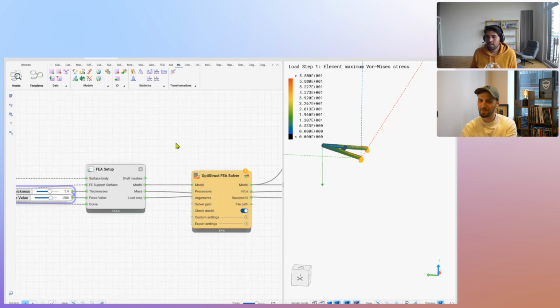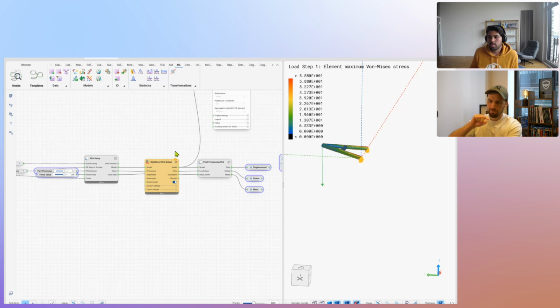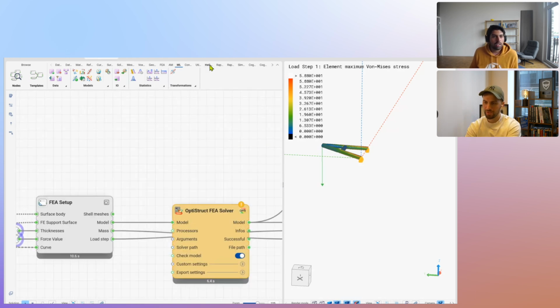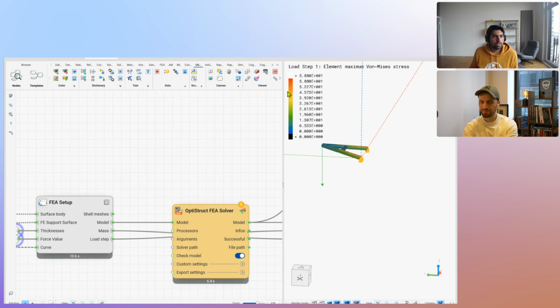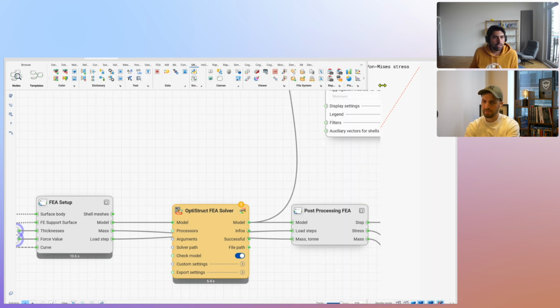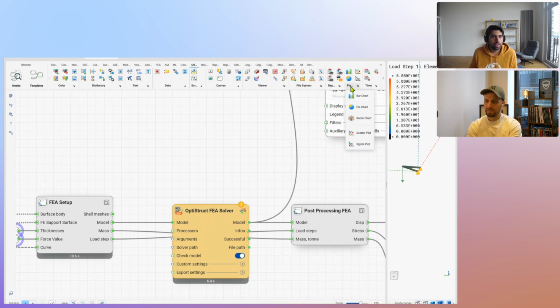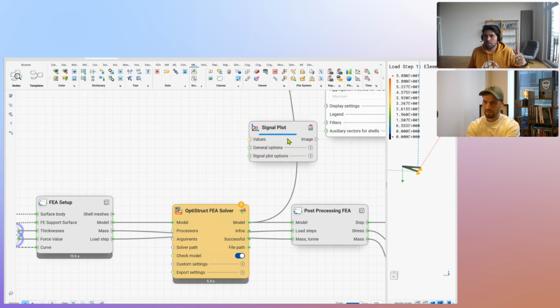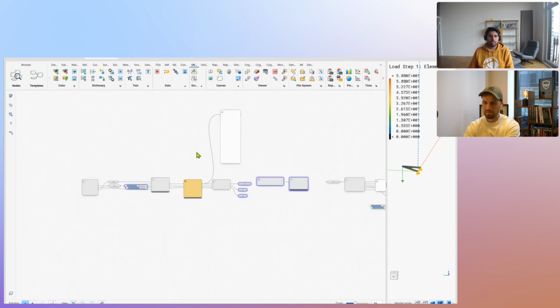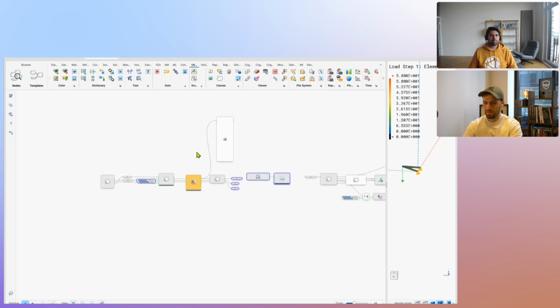But I think it's also cool in Synera because you would be able to run a number of experiments inside Synera and then plot, for example, the degrees of freedom and the stress. Exactly. You can also have your own plotting functionality. So you can write a custom sensitivity analysis logic, build a plot of some values, see how they were spread and how the values varied, and find the ideal element size for you. Really cool, Ram.